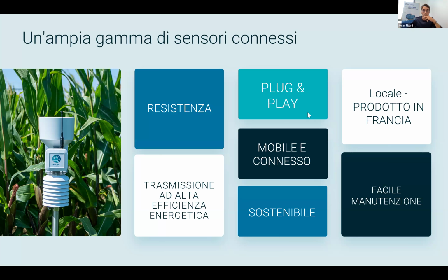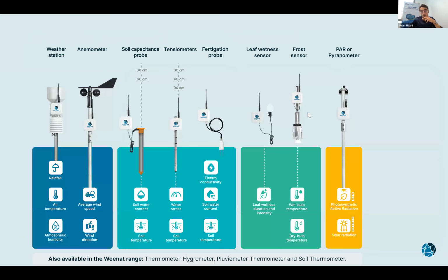And all our systems are made on the same basis, which is independent sensors, completely autonomous, to be installed anywhere. Which is one of the reasons why we also work in agrivoltaics, because sometimes there's a really remote installation. We can install the sensor anywhere without the need for further cables or communication. So any module has the same communication. We work with different kinds of communication systems, LoRaWAN, Sigfox, NB-IoT, LTE-M, to adapt to whatever coverage is best in any situation.